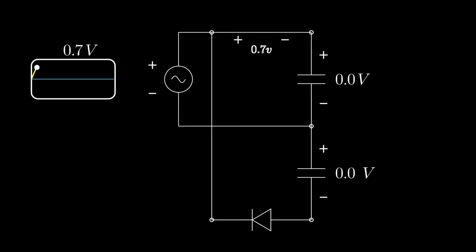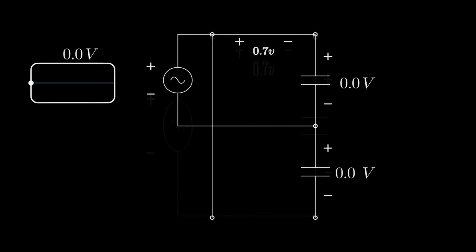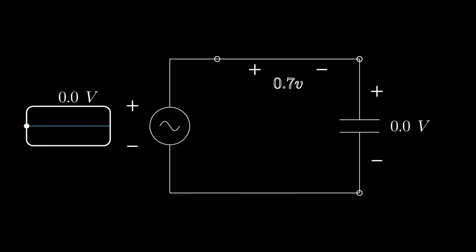The opposite happens to diode 2. We apply a positive voltage to the cathode, so again assuming an ideal diode, we can replace D2 with an open circuit. This effectively removes one of our caps from the circuit completely, so we'll just hide that for now so we don't have to worry about it. Now, this circuit is super easy to analyse. We can see that this positive voltage minus the voltage drop is going to charge C1 to about 20.5 volts.